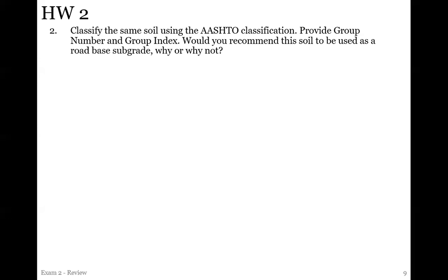So that's the tricky part. Even though it's a roadway, any structure on the road, like a retaining wall or a bridge, or even those toll gantries, those big signs that are like 20 feet tall, any type of structure near the road still uses USCS. So just the roadway subgrade and the typical driving lane and stuff, that is used for AASHTO.